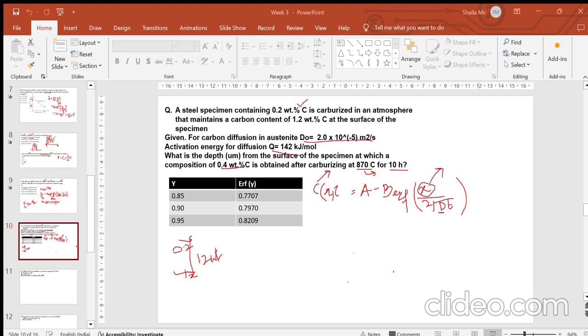This is again based on your diffusion coefficient and the relationship that varies with your temperature. Now you are given at 300 Celsius the diffusion coefficient and activation energy for copper and silicon. D1 is given because this is your diffusion coefficient, your activation energy is given, and you have to calculate the diffusion coefficient at 350 degrees Celsius. So you are given D1 at 300, and you know QD also. Based on your equation, what is the equation?